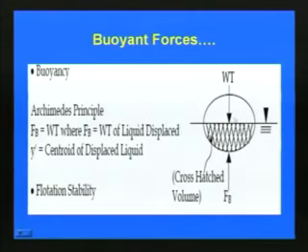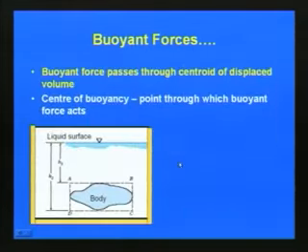With respect to this buoy, some liquid will be displaced, so we can calculate the weight of the liquid, and that gives the buoyant force. Then we can determine the centroid of the displaced liquid, so that we can see where it is acting. The buoyant force is very important, especially as far as static fluid is concerned, as we have discussed here.